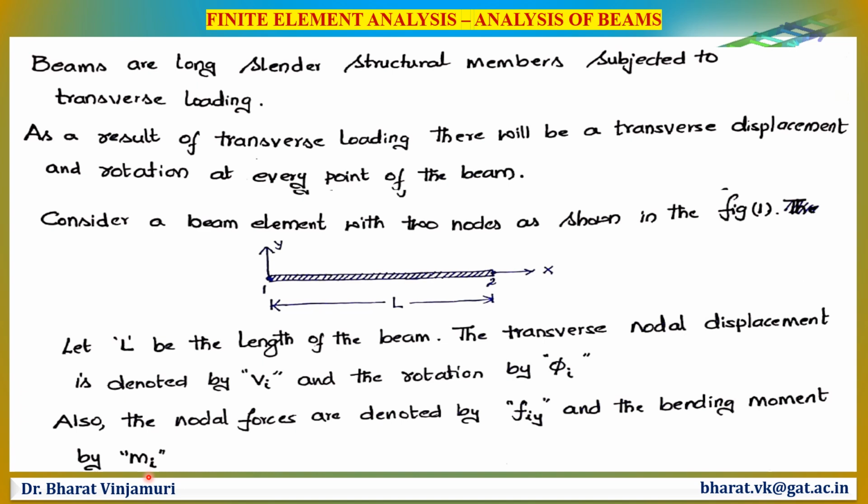Here i talks about the node number. So these are the notations which we'll be using throughout the entire session. Where it has a transverse displacement vi, the slope is denoted by phi i. Fiy will be used for shear force, as well as M for the bending moment.